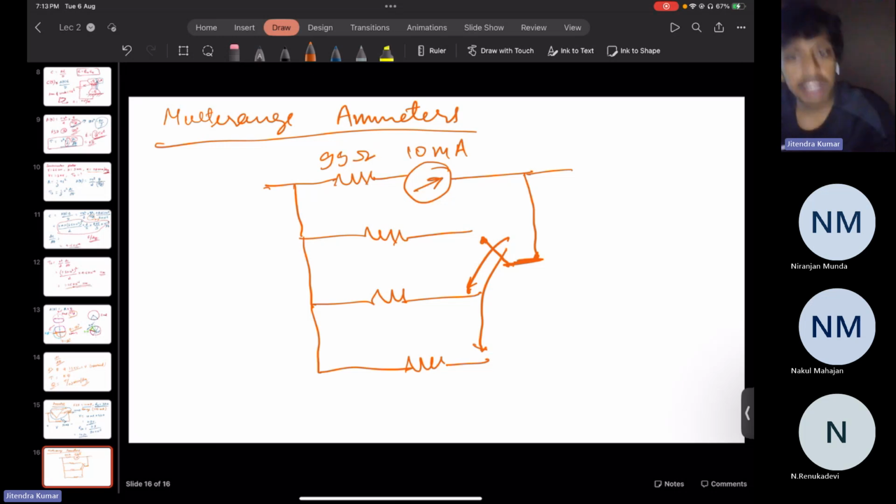And the reason or the answer for that is, if you are going to measure 10 milliampere and you have an ammeter with range of 100 ampere, it is going to give you a lot of error. So you will not have a precise and accurate value, and very far from accuracy. So that is why we generally want ammeters which have the range very close to the value we are going to measure. That is the concept behind it, and how all of them will vary, we will also see with a problem.